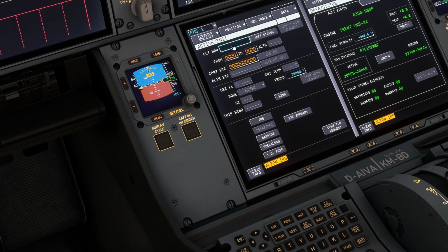Go to the flight number. Now you can use the keyboard by pressing the left control key and entering your flight number, which really doesn't matter for this flight. We are flying Echo Delta Delta Mike, return, and again Echo Delta Delta Mike, return. There is no flight plan, of course, no company route for that, and the flight level will be 70 only. Should be a short flight, and the cost index doesn't matter, but we take 2.5. That's all I do here.